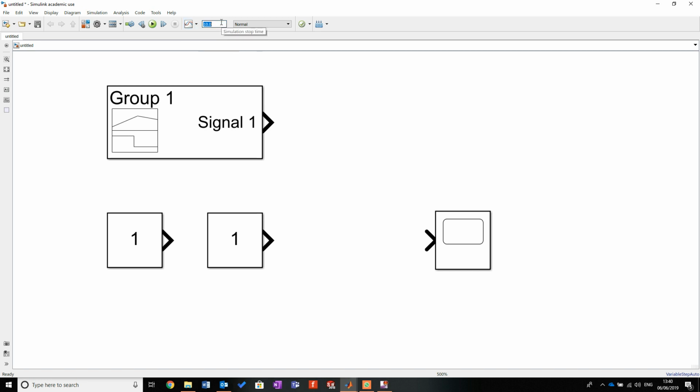Further, we have time of simulation running. As you imagine, 1 second, 200 seconds. If you're running continuously, INF. I do need to warn you, do not run this if you're not ready to, because sometimes you can spam the memory, as this thing will just keep running on an infinite basis. Basically by typing INF you're saying I don't want a specific time frame, I just want you to keep running and take sample blocks.